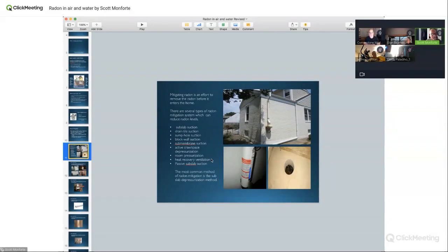So here's the problem. I've had a big, long talk with the radon guru out there, Bill Broadhead. He said that they're looking into, and this is in the future, making some sort of containment area for the fan that has an outside vent. So now if that fan were to leak or those fernco couplings were to dry out and it would blow into the attic with all that spray foam, technically, even though it's not heat or AC, it's considered a conditioned area. It's part of the house now.